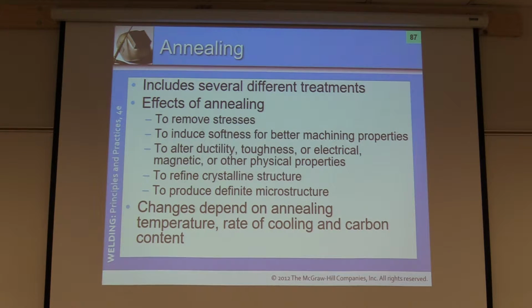Another form of annealing is stress relief annealing. It is usually applied only to low carbon steels. The purpose here is to relieve the stress caused by working of the steel, such as in welding. The material is heated to a point just below the critical range and allowed to cool normally. So there are two different things we can do with annealing, okay?